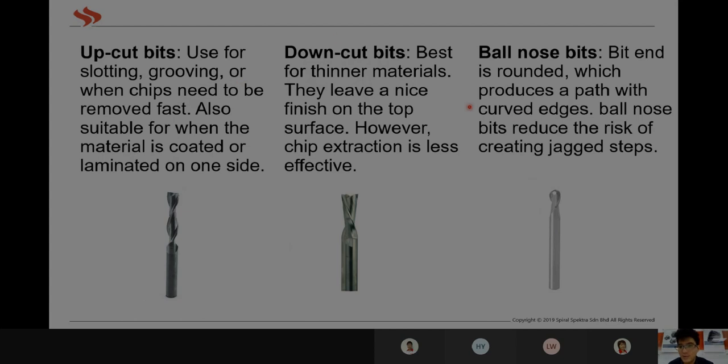Now, ball nose bits are technically not sharp at all. Their bit end is rounded, which produces a path with curved edges. They are more for detail cuts and engravings, in case you want a round edge, and then you use a ball nose.